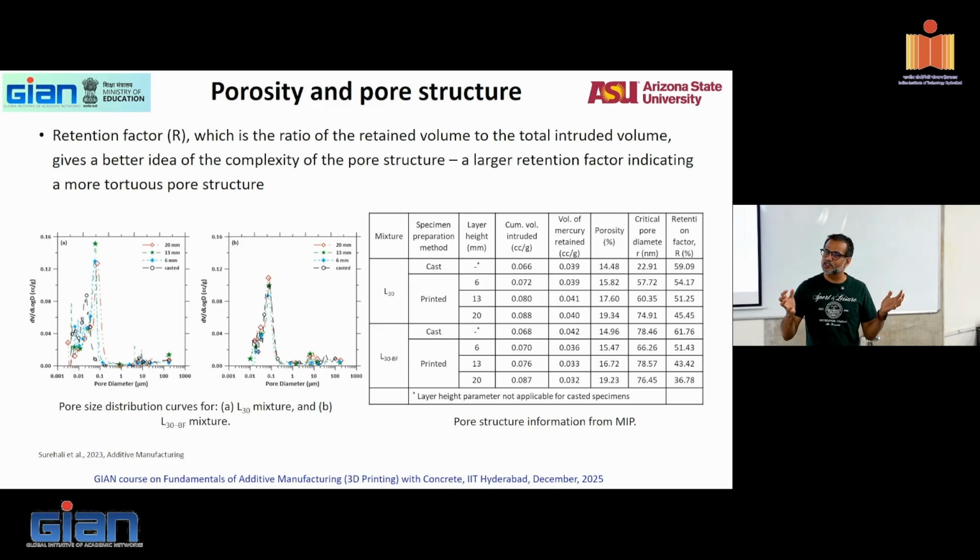It is a hydrostatic pressure. It's under a triaxial state of stress. And in materials that are under a triaxial state of stress, you will demonstrate an extremely high apparent strength. That is why, if you have done your geotechnical class, you never do a uniaxial compression test on a soil, because you can't. Soil is a granular material, it just compresses and breaks away.